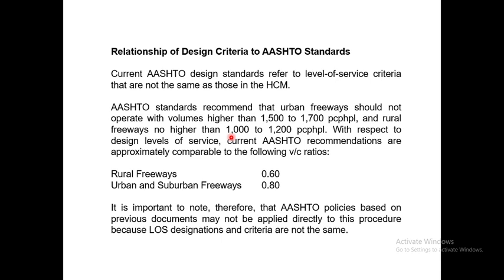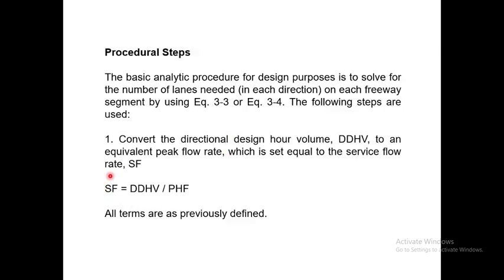Okay, so again, in the first step, we need to calculate the SF, service flow. Whatever you want to do, you have to first calculate the SF. Whatever value we give you, if we give you the hourly demand value, you have to divide it by PHF. If we give you the directional design hourly volume, you have to again divide it by PHF to find out the SF, service flow.